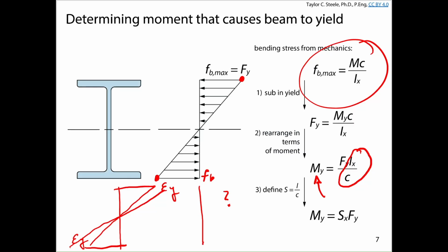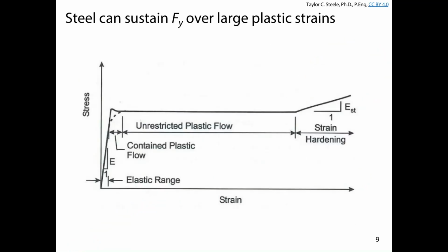So we can probably exceed the yield strain and try and take advantage a little bit of the additional strength or some of the ductility of steel. We will go back and remember that steel is a very ductile material, and so within the elastic range it's very strong and it's very stiff, but once it reaches the yield strength, we have a significant amount of plastic deformation that comes from yielding of the steel.